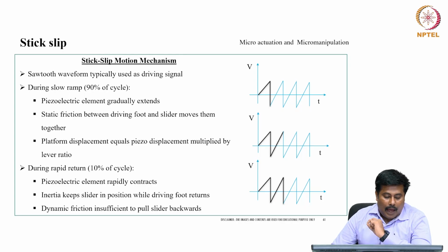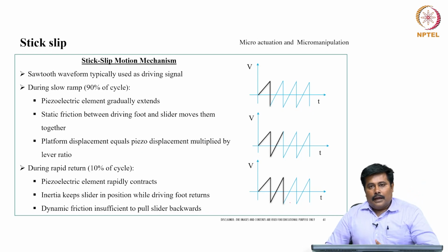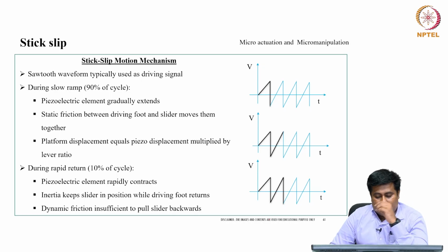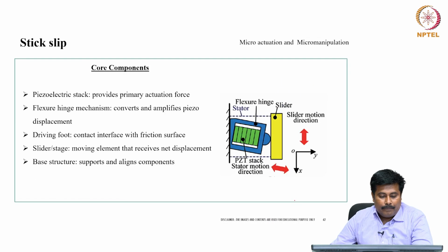However, during a rapid return, that is around 10% of the cycle, the piezoelectric element rapidly contracts and inertia keeps the slider in position while driving the foot return. So the dynamic friction is insufficient to pull the slider back.